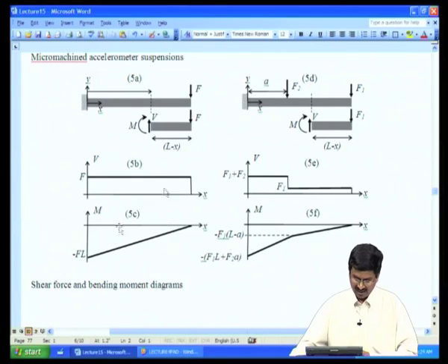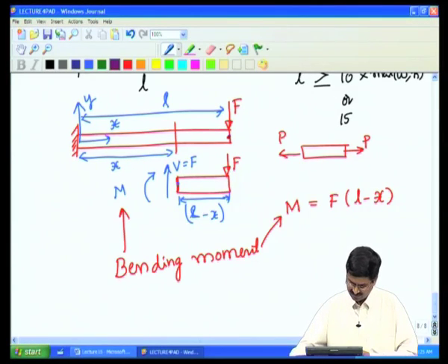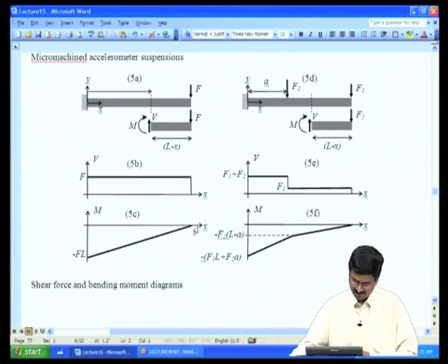and then as we go it is going to be minus F over L, because of our sign convention here. If we go back and look at the sign of the moment here, this is F times L in the clockwise direction, this has to be counterclockwise direction. We say that the bending moment is negative, and that is indicated over here, that is our sign convention. Bending moment is negative for something like this. When I apply force, it is going to bend like this in a convex fashion, and that is the negative bending moment's effect.